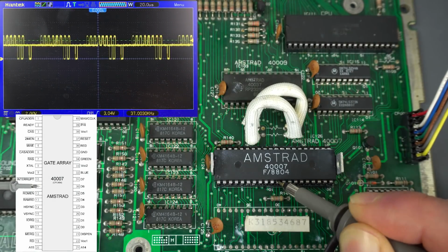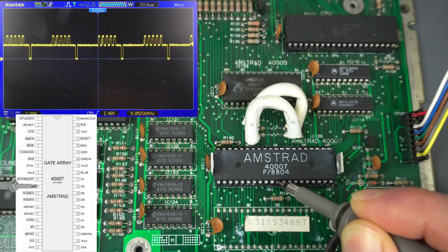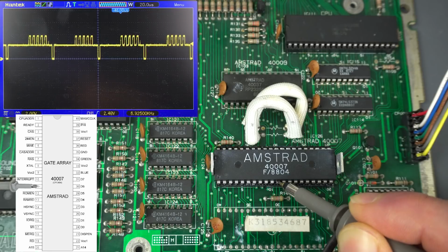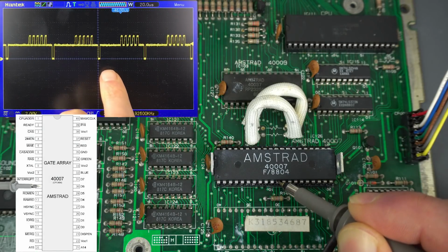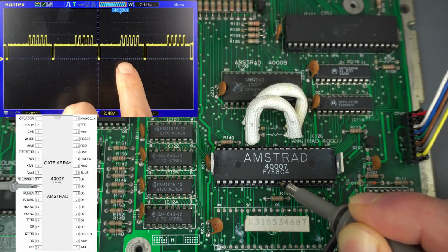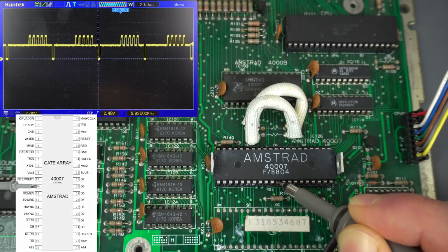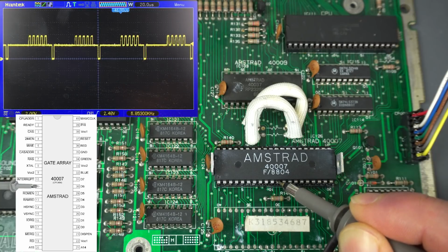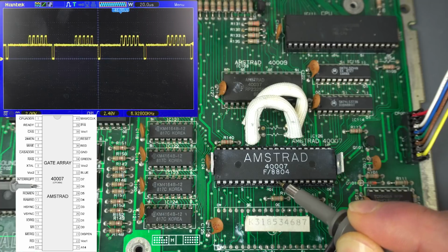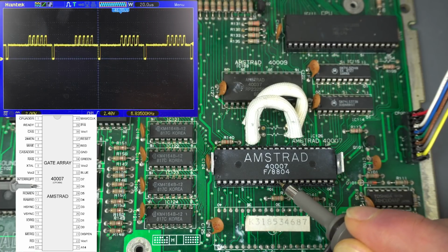What about the frequency? Is it more or less the same? This sync signal should happen with the horizontal sync, which is every 64 microseconds. That's not even right. That's 1, 2, 3, 4, a little bit more than a half times 20 microseconds. So that's not even happening every 64 microseconds. What is this? Am I in the right pin? I am on the right pin.